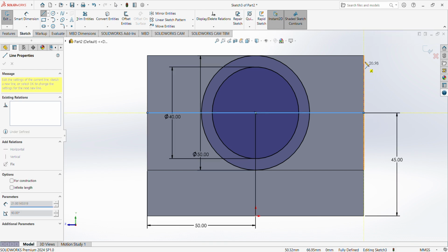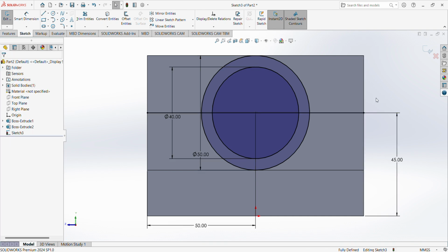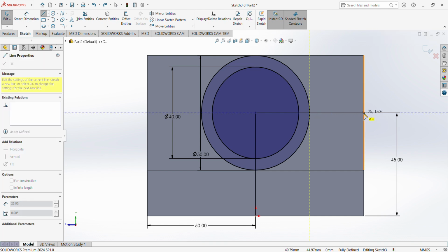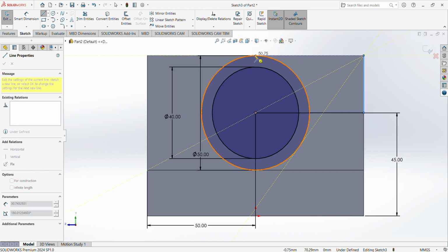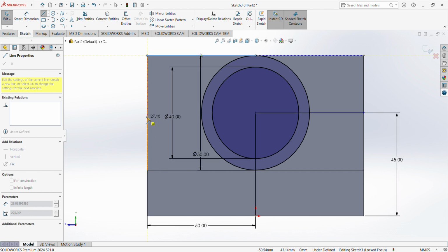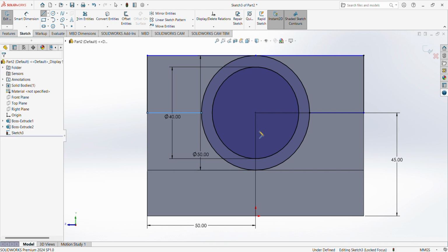Then when you are doing your extruded cut, select the area you want to work on. You can do that, or at the same time, let me escape. Ctrl Z. At the same time, you can take your line tool starting from one edge of the circle. That is here. You go straight down here. You go up here. Then we go to this point here. Okay. Then we continue again. You can tell us to go to that point and just go straight and draw to that end. But I just said for accuracy. The next one is also at the center of the circle too. So we stop here and then we come to the edge of the circle. And with that, we are done. Just escape to leave the tool.